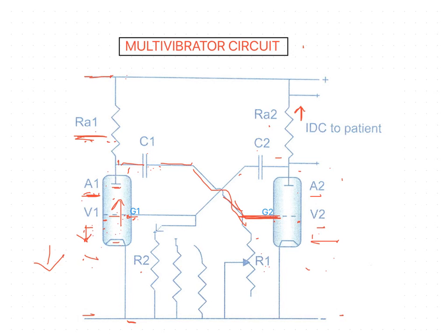The condenser C2 is in parallel to V2, and so the potential difference across it is the same as that across the valve. It is charged at the beginning of the action, the left hand plate being negative and the right hand plate positive, but during the above sequence of events, the potential difference across V2 falls, and so that across C2 also falls.